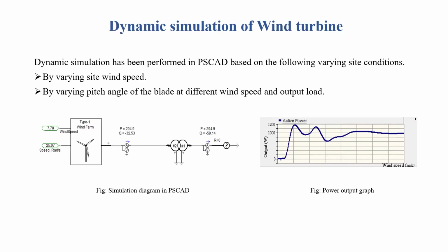Let's talk about dynamic simulation. In steady-state analysis, we considered fixed input for pitch angle and wind speed, but the actual output depends on the variable inputs according to the site condition. These variable parameters will change the average output of our proposed system. So in PSCAD, we have used variable wind speed and pitch angles.